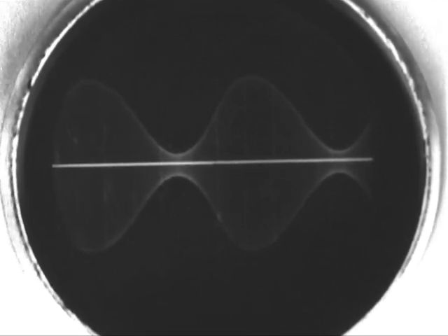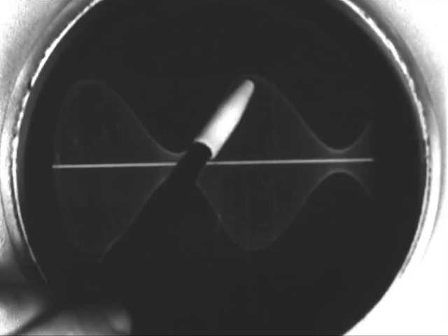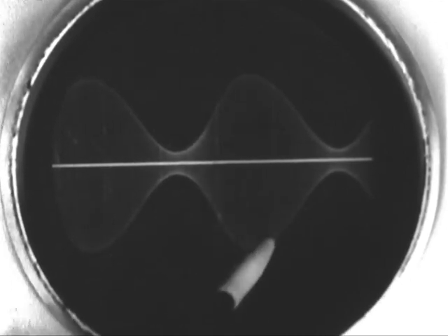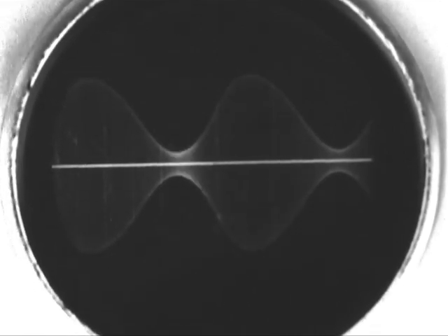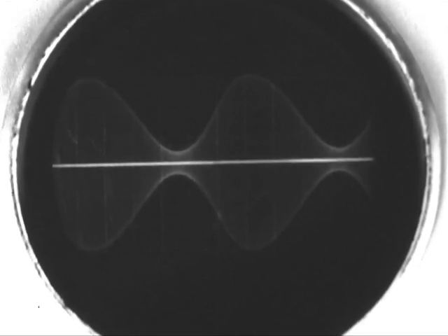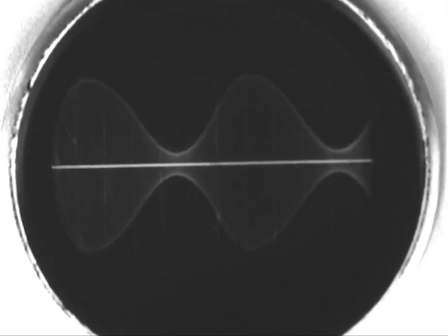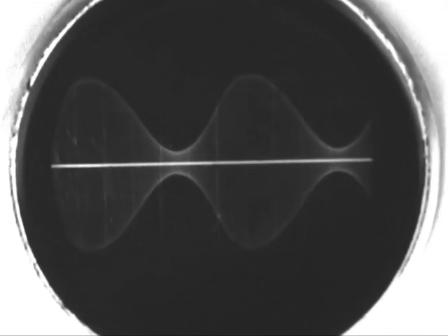The audio frequency is contained in the fluctuating amplitude of the IF signal. If we wished, we could recover 2 audio signals. One is a fluctuating positive voltage, the other a fluctuating negative voltage. These signals are both the same and contain the same information, but they are 180 degrees out of phase with one another. In this circuit, we will recover the negative signal. You'll see why in a moment. Our detector will remove all the positive voltage above this line to prevent its interfering with our recovery of the signal.